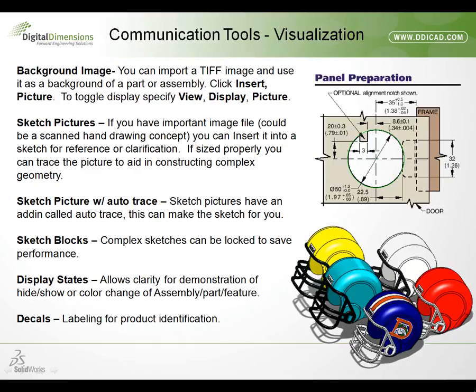If you plan on making your own images for use as sketch pictures, then a lot of pre-processing before you bring the image into SOLIDWORKS will be required. In fact, if you plan on taking digital pictures of the parts you want to make sketch pictures out of, then you're going to need to make sure that you have a light background that the part is put on top of, so that when you create your digital photo, you'll have a clear definition between the boundary of the part and the table behind it.